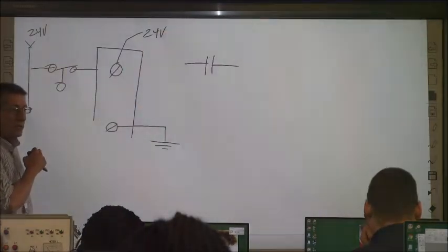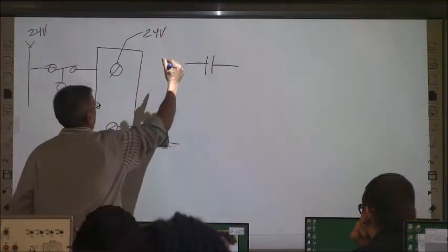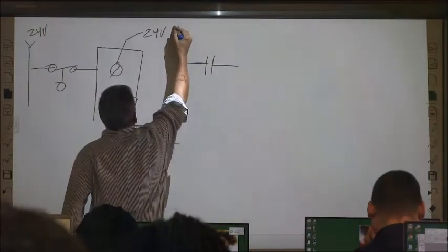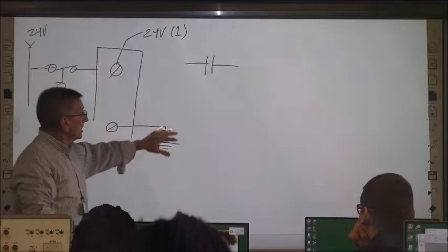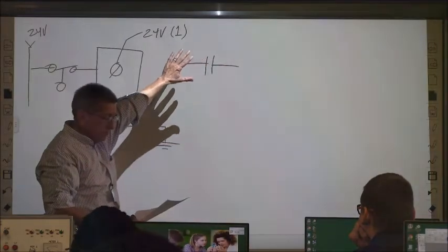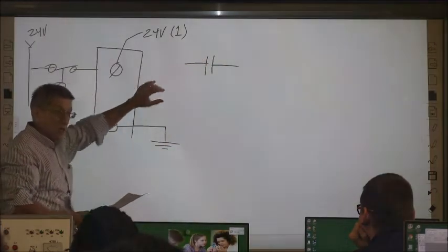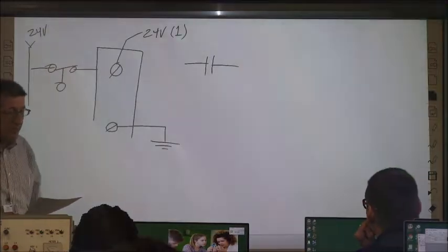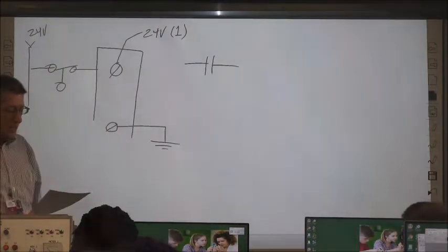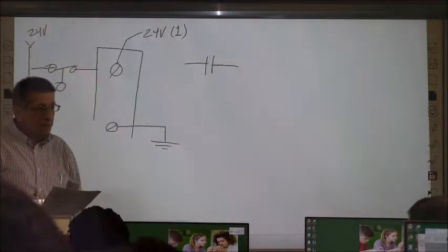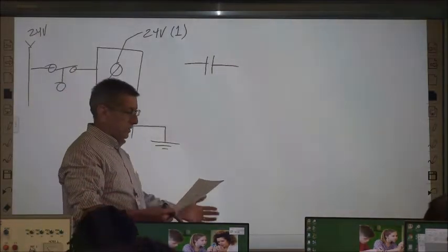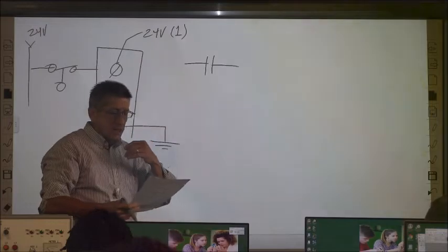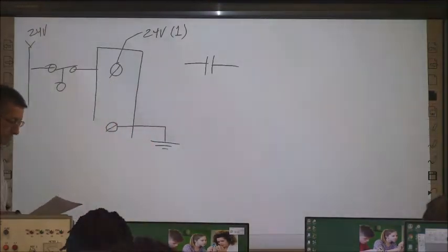What's the value in the PLC? A 1? Yes. It says we have this XIC instruction, but it does not have logical continuity. A, can we eliminate that? No, that's normal for a normally closed switch that uses an XIC.